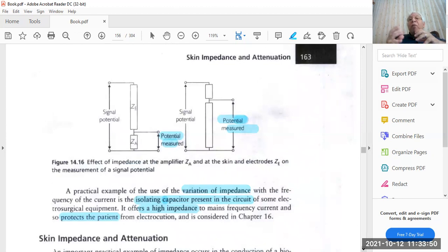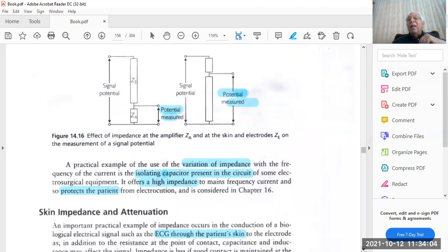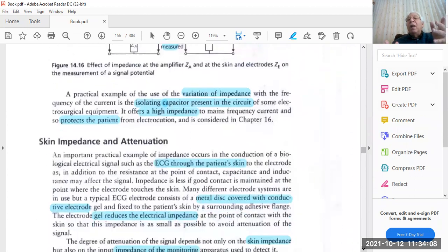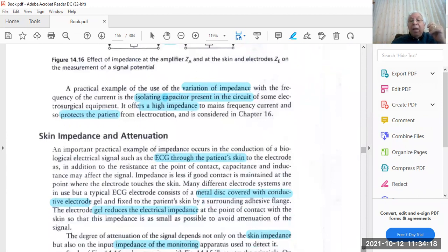So this figure is showing the potential created by attachment, whether the impedance of the amplifier is high or low in comparison to the skin, to yield a better configuration, so that it's better to have a high resistance of the amplifier with a low resistance of the skin, so that we can get a proper signal.